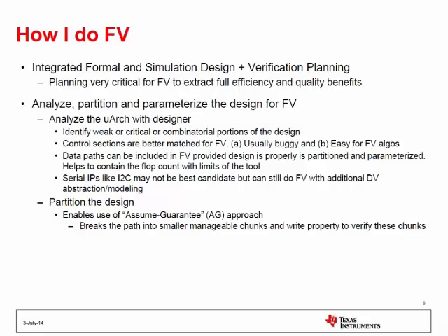And control sections. Control sections are better for us mainly because this is coming from the vendor-based tools, because we are not focused more on data. Since we synthesize our data paths, we don't use hard-coded data paths like the other speakers have talked about. We don't have that issue of making sure our data paths are indeed what they're supposed to do. Our main focus is going to be on the control part. That is where we are going to find a lot more issues, and we found that it is difficult to verify all the corner cases and coverage points in a control. If you are able to structure it in a proper set of assertions, you'll be able to get much more quality out of your control path.